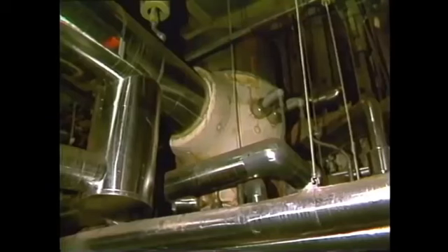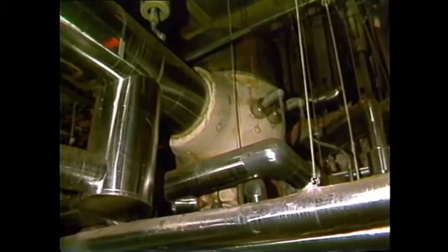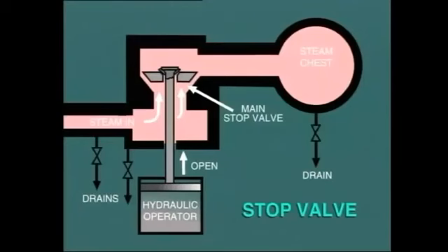An extremely important test maneuver is the exercising of the turbine's stop valves. The test circuit allows the stop valve to partially close and then open again. This test is performed daily in many plants, and the objective is to make sure that the stop valve does actually move and not remain frozen in the open position, as has actually occurred on some occasions.